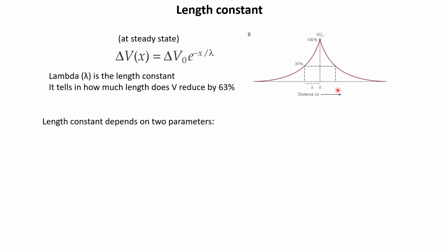At different values of x, different steady state values will be reached, and we are looking at the distribution of these steady state values. Since the charging has been over and the values are not changing over time, we can ignore the capacitance, because capacitance only affects the initial charging period, but once the charging is done, the final value that is reached does not depend on capacitance.